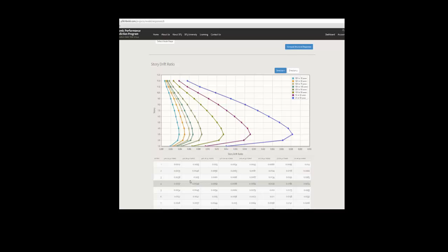But I think it gets past most of the limitations, with the exception of the elastic analysis limitation. And then I think a second part of an answer to that question is the USRC requirements specifically say, I forget the language, any rational method for predicting structural response. So if you use some modified form of the P58 simplified method, that's an enhancement on that, all the better. That's allowed in the USRC approach and process.